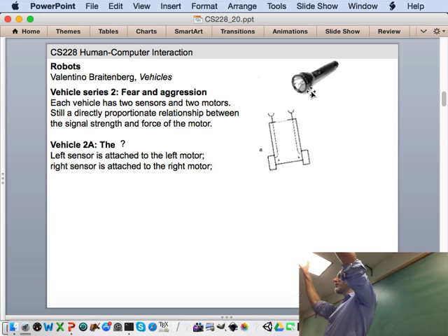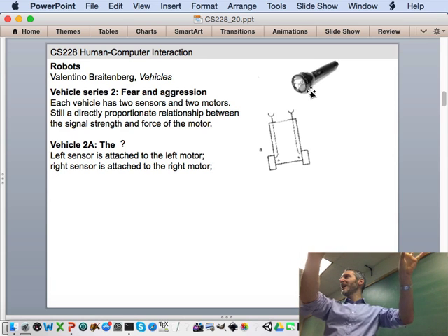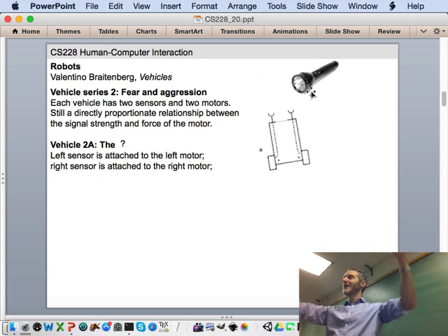Let's talk about the wheels. The values of both light sensors drop slightly. They spin more slowly, right? So it's turning away from the light, but it's slowing the rate at which it turns away from the light. And as it turns away, maybe the total amount of difference between the two light values begins to equalize, which means the curvature at which it's turning away from the light also increases a little bit, starts going a little bit more straight. Let's say these are omnidirectional lights, meaning it's still sensing the light behind it, but at a lower rate, so it slows down.